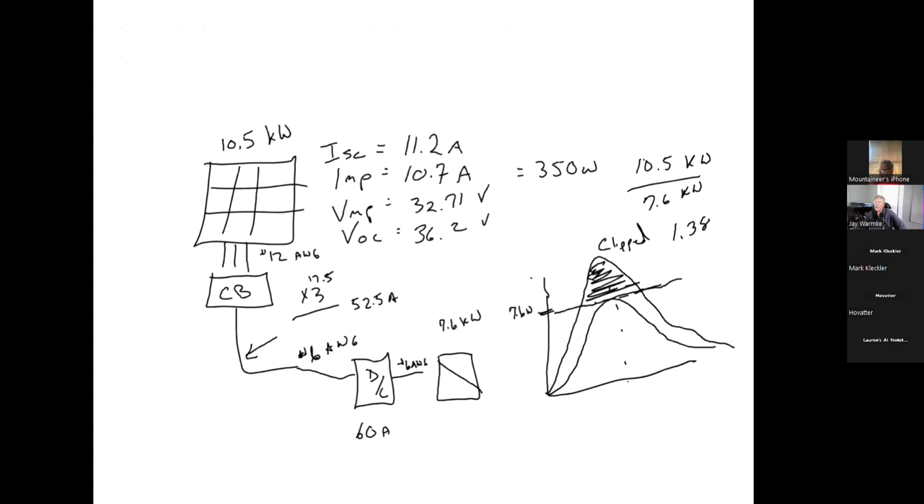But the other thing that you've got to take into account is all of this power generation at the shoulder is additional power. So this is power I'm generating that I wouldn't have generated had I had an array that's the same size as my inverter. In many cases, the power that's clipped is equal to or less than the extra power that's generated out here in the shoulders.